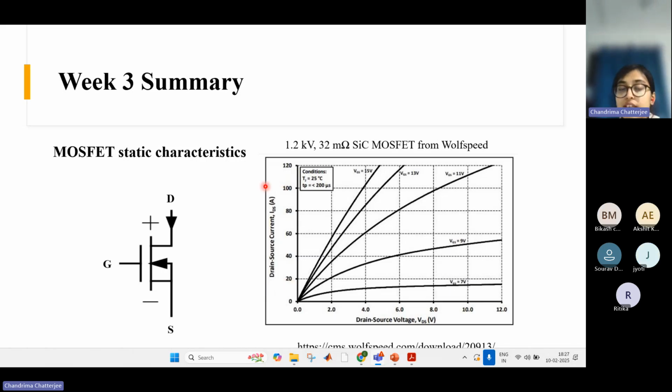So for static characteristics in x and y axis, you will have some current or some voltage. But if we see the dynamic characteristics, there you will see the current and voltage waveforms with respect to time. How the voltage and current waveforms vary in on condition, in off condition with respect to time. So that is called a dynamic condition.